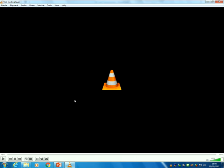The origin of the name, hot tap, how is it? Why did you say that? Well, it originates because tapping is a drill. So if you drill into a pipe, it can be considered tapping. The reason it's hot, if you do any work in a pressurized area, if you're working under pressure, you tend to have a hot work permit. So it's based on that. It's recognizing the fact that you're going to be drilling into a pressurized system.